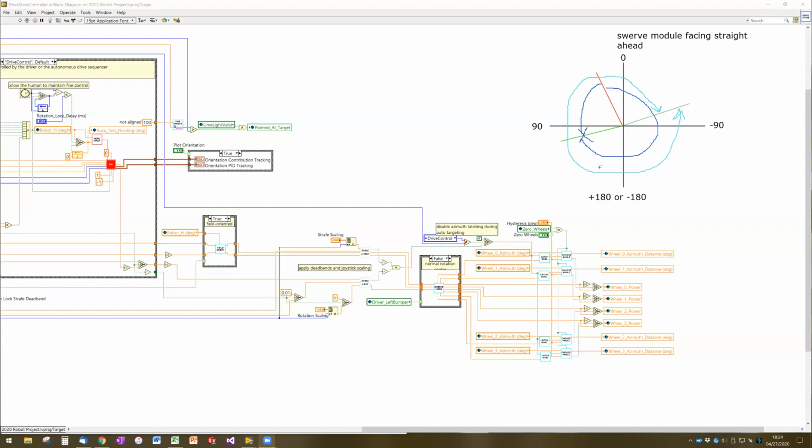And the nice thing about it is we can do those two things simultaneously, because the way that we're going to choose between the angle options is by going with the angle option that has the smallest angular distance. That's the one that's going to take us the least amount of time in order to move the swerve module. Does anyone have any questions about that concept before we go into the math?